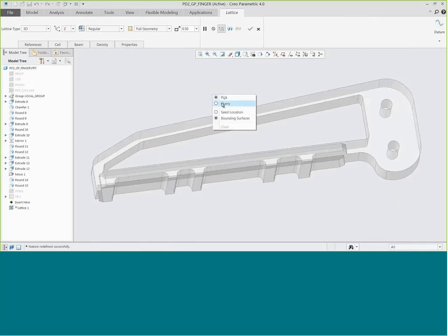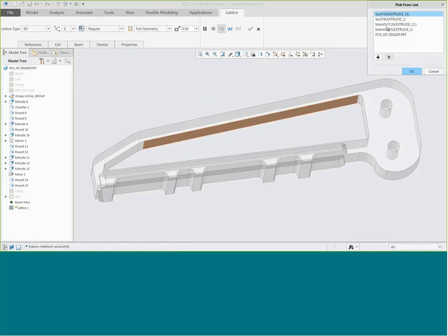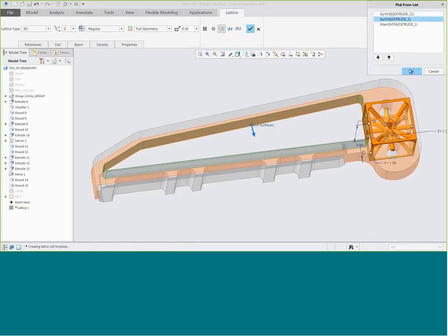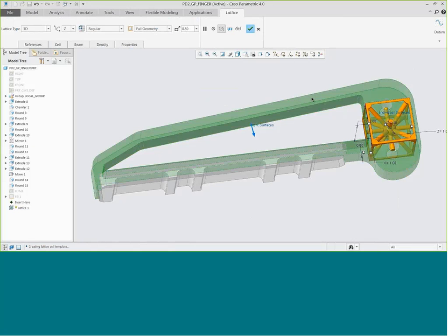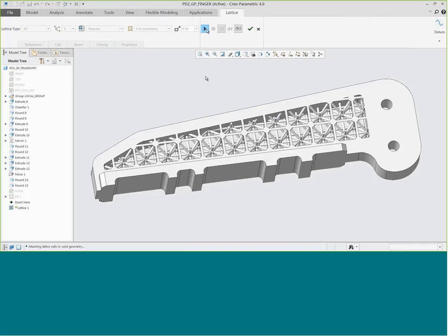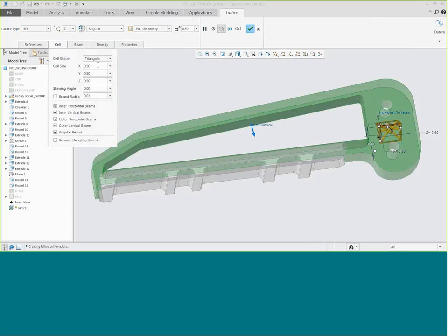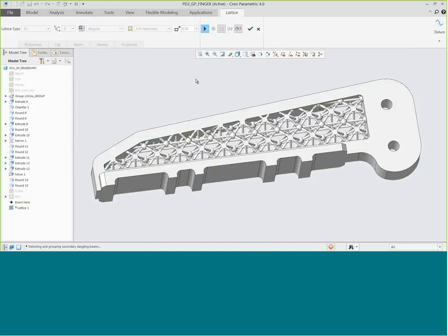So basically, I'm just showing you all the different types of lattice structures that you can create. I start off by creating a regular structure. Then I created this. This is a 3D lattice type. You can see up in the top left of the screen, it says it's 3D. I can change the size of this, so that's just scaling it to 50%, or I can make it bigger, and there we go, there's the lattice. I can then change it from a square to a triangle. If I want to, I can take away the ball that's in the middle. I can change the way that it connects all of these things together, and then go and examine that.